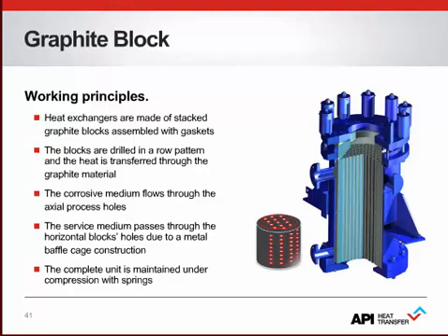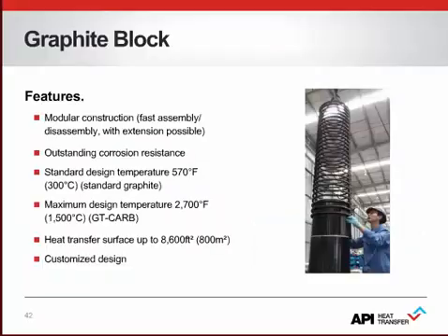On the right side, you can see a typical block graphite heat exchanger. And you can see next to it a small graphite block that is installed in such a heat exchanger. Graphite is a quite fragile material that on the other side comes with a very good thermal conductivity, much higher than stainless steel, for example. Within the last years, the graphite heat exchanger was improved on performance as well as on stability. But the most important feature is the outstanding corrosion resistance.